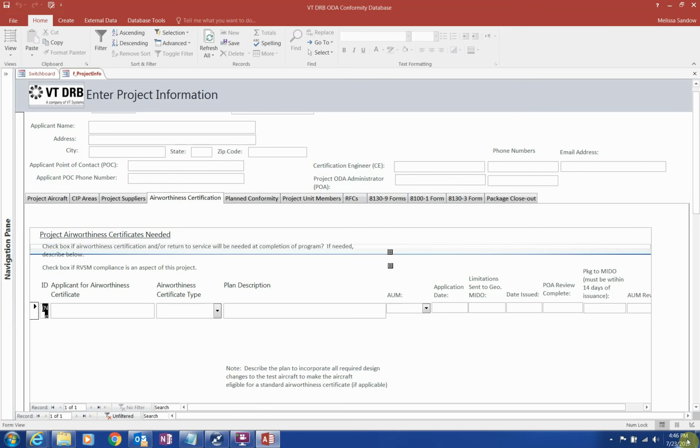An aircraft normally has a standard airworthiness certificate, which means the airplane meets its type design and is shown to be airworthy to fly. However, once something has been modified, it no longer meets type design until an approval is in place. So when we change the airplane to prototype and test during a project, its type design is in limbo and is no longer known to be airworthy.